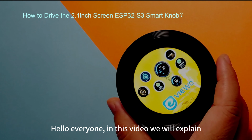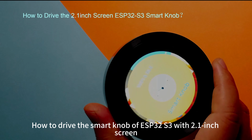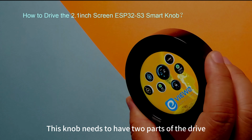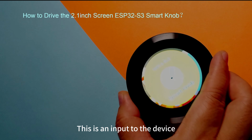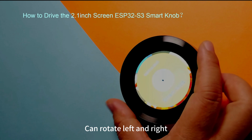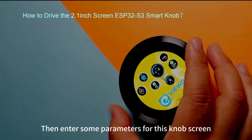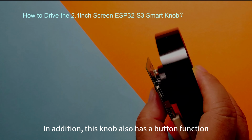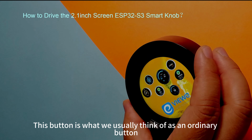Everyone! In this video, we will explain how to drive the smart knob of ESP32-S3 with a 2.1-inch screen. This knob needs two parts of the drive. Part of it is the rotary encoder. This is an input to the device. The rotary encoder is the physical part of the knob, which can rotate left and right. Then it enters some parameters for this knob screen. In addition, this knob also has a button function. This button is what we usually think of as an ordinary button.